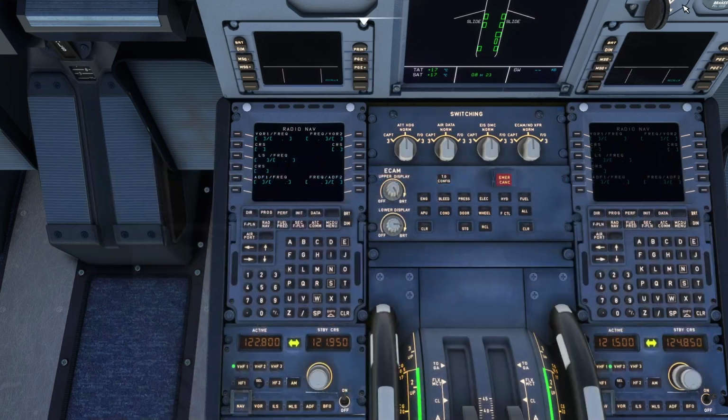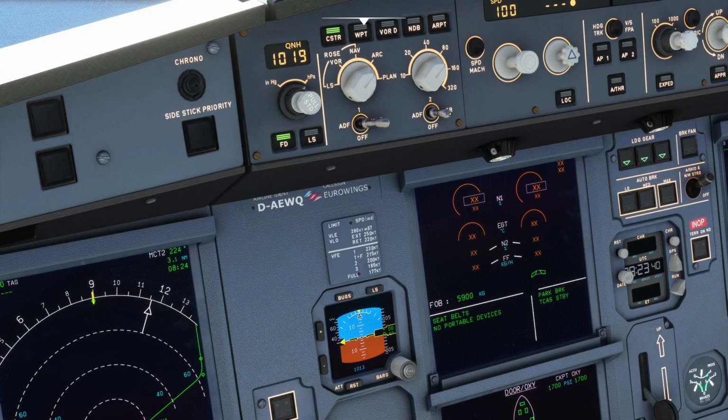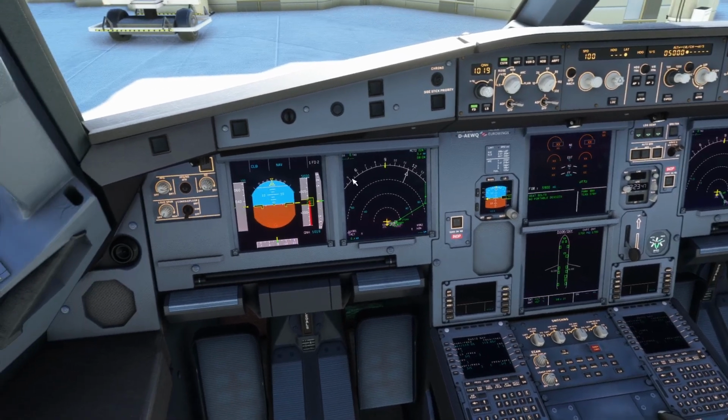So we can go Manchester 113.55, stick that in the VOR 1 frequency, and 113.65 for Honolulu. So there we see Mark Charlie Tango, and 113.65 will be Hotel Oscar November. That will be that frequency for VOR 2. And then over here on the flight control unit, we can turn on VOR1 and VOR2 displays. And there those arrows will point in the direction of the VORs.